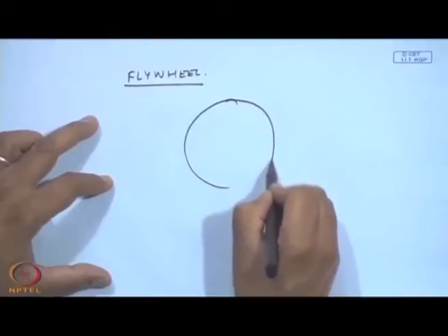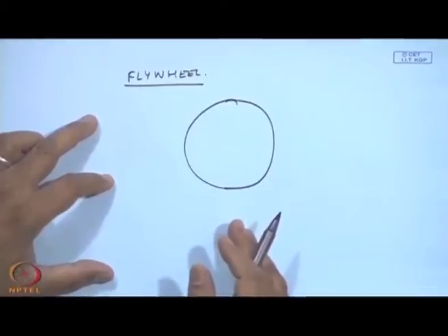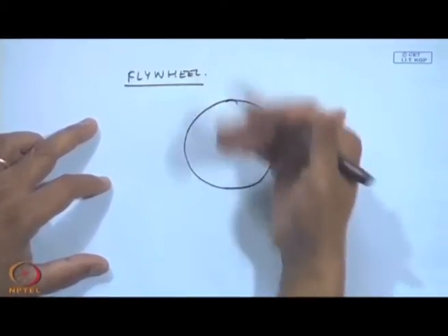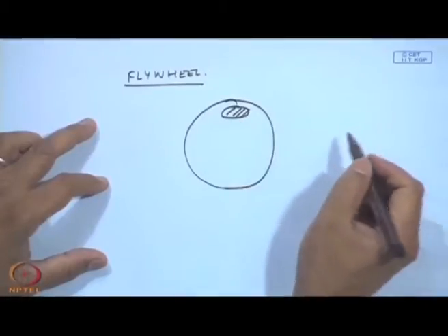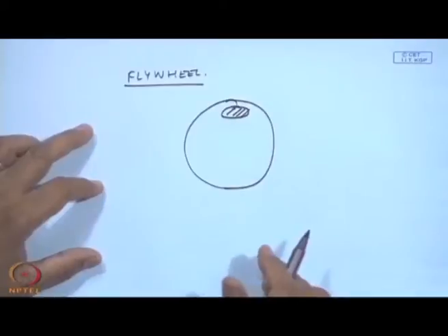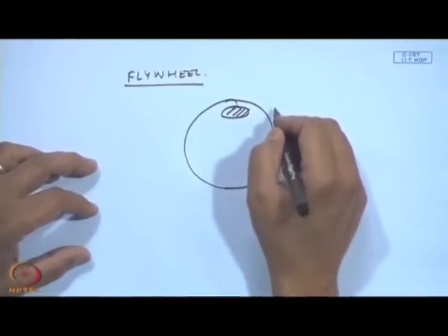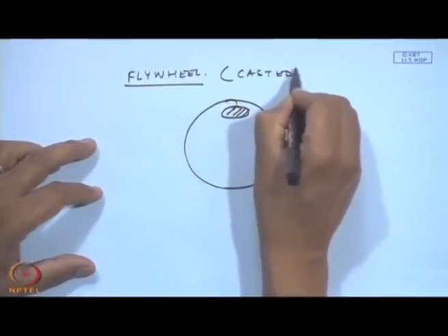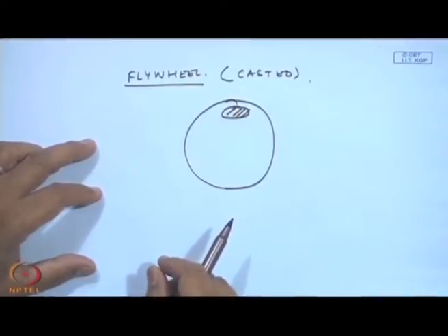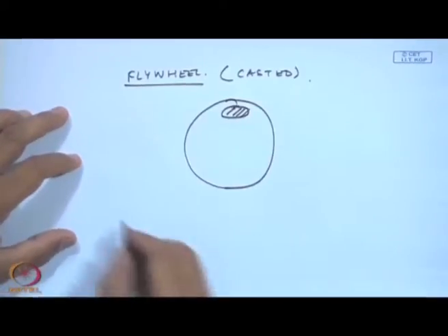But I am talking about single, 4-cylinder, and 3-cylinder engines, wherein the flywheel is mounted after the clutch, after the crankshaft, so that we reduce the cyclic engine variations. And imagine such a flywheel has an amount of unbalanced mass. This is going to give an unbalanced force onto the shaft, and this is not desirable, and usually flywheels are cast.